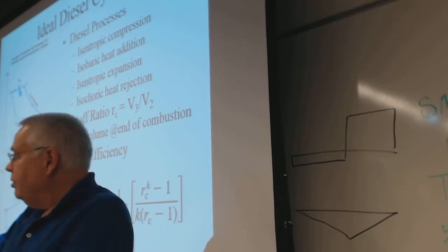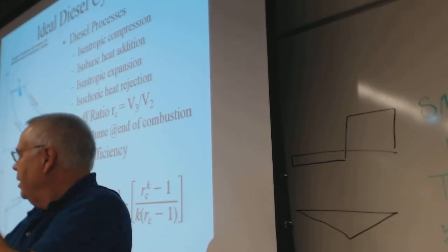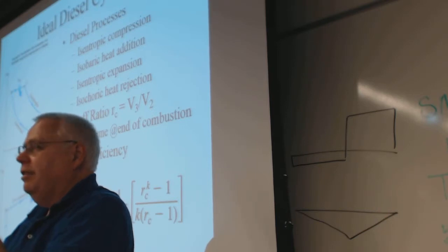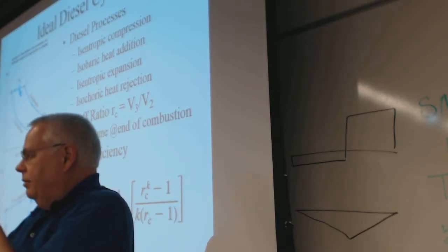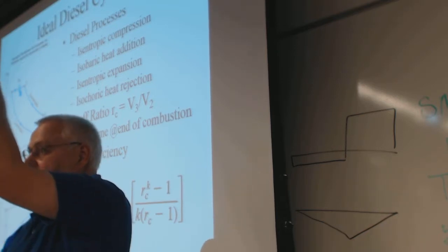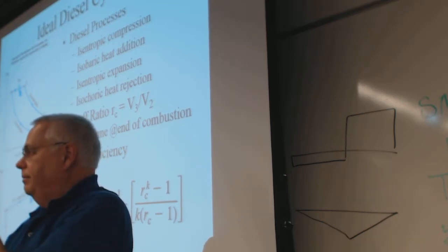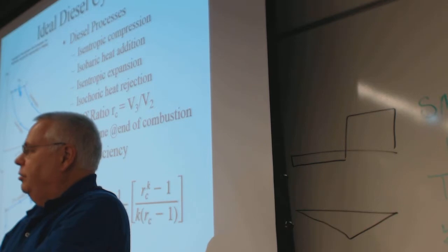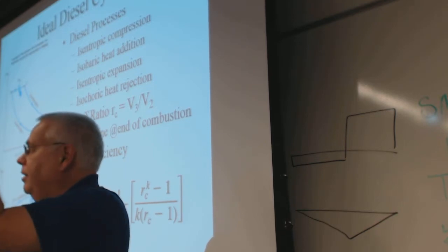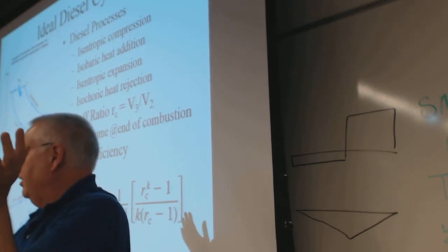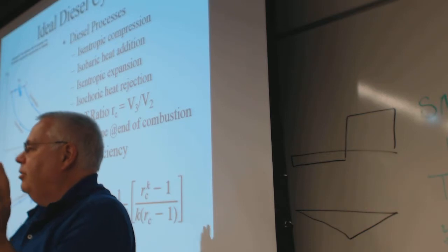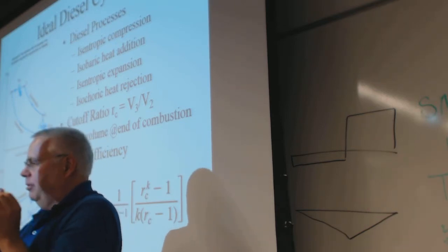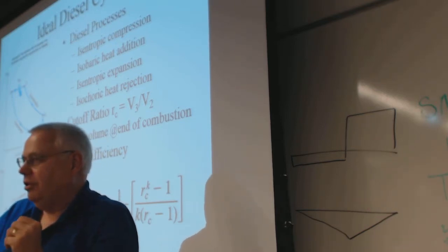If that value is 100, so you drop to an enthalpy of 100 that has the same value for entropy as the high value. That says you could have possibly converted 1100 minus 100 gets you 1000 kilojoules per kilogram. The turbine doesn't have more energy than that available to convert. If it was a perfect turbine, it would get you that much work.